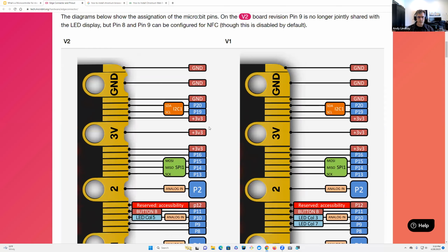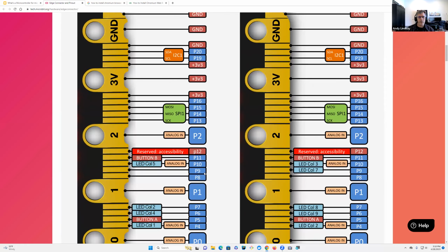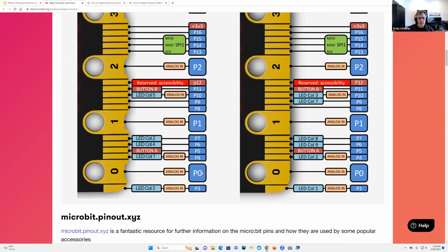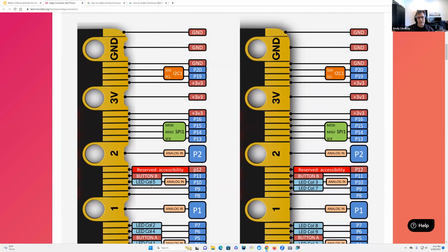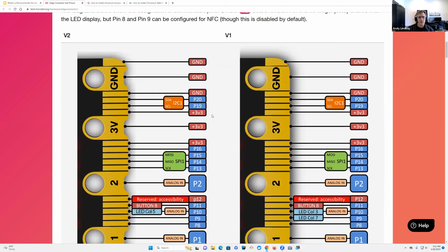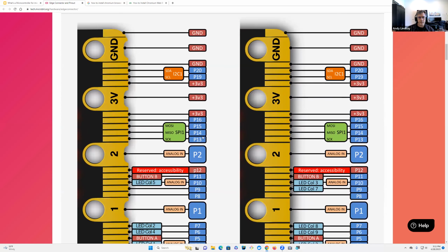And so it's good to have this information about what's on the microbit so that you can find a pin like, pin 0 is obviously nice and empty. Pin 2 is obviously nice and empty, and so on and so forth. But some of these get a little bit more complicated. And the easiest thing to do is just to go for the pins that don't have any extra features initially. Some of this I2C stuff is in my mind a little bit arbitrary. There's some special features up here. I have pretty much ignored them. Basically, you'll see that, oh no, pin 16 is empty.